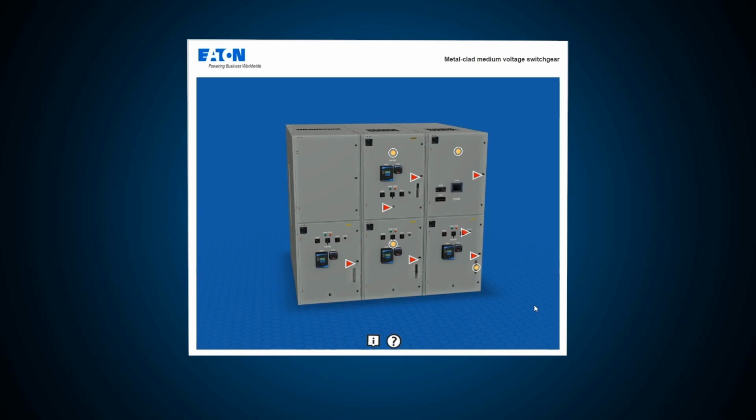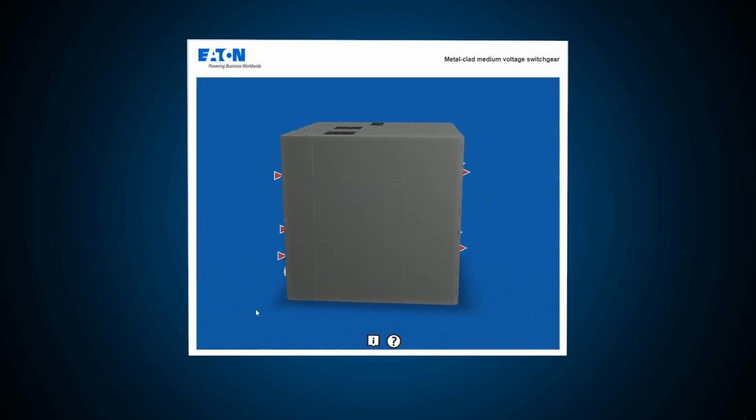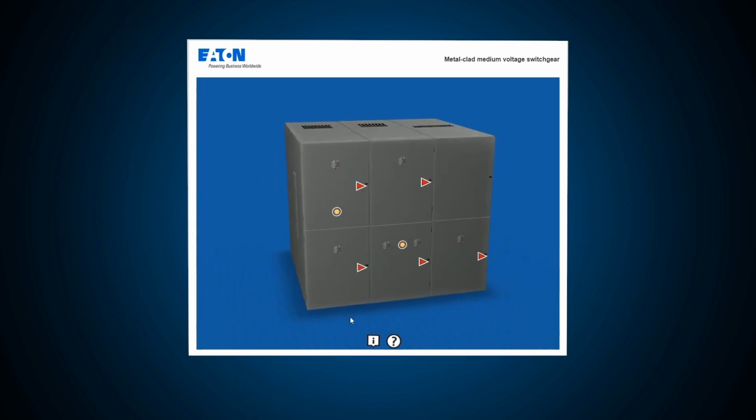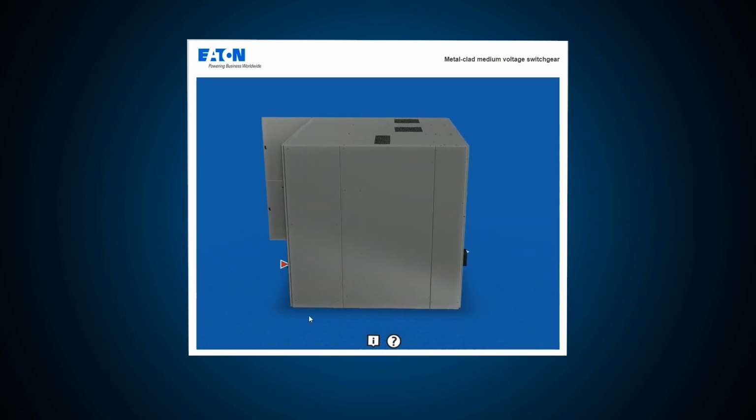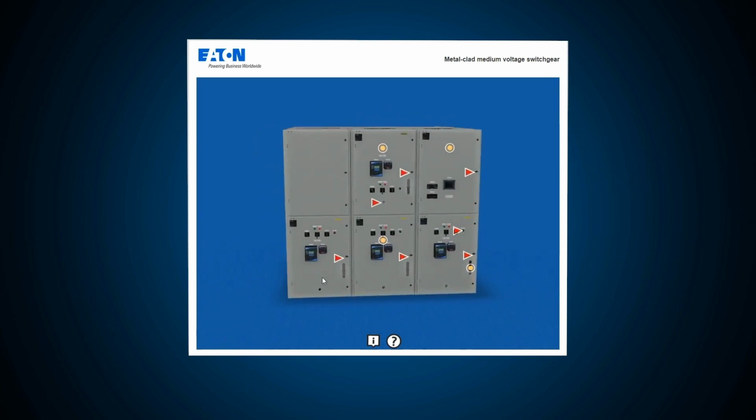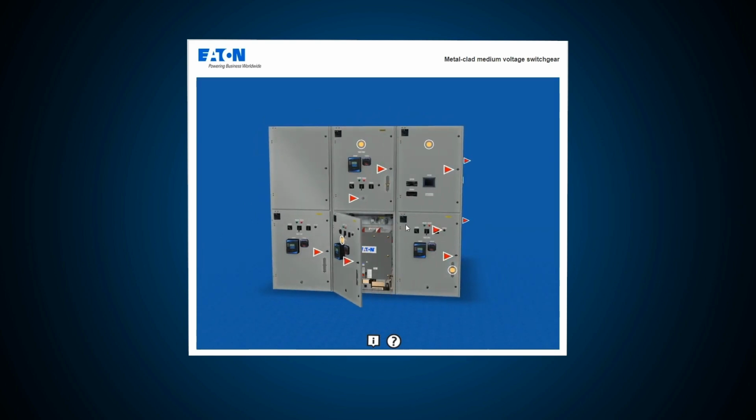Air insulated switchgear, AIS, is defined by the IEEE C37.20.2 standard for metal clad switchgear, and the IEEE C37.20.3 standard for metal enclosed switchgear. In metal clad switchgear, all electrical components, including the incoming bus, the outgoing bus, instrumentation, and main circuit breaker or switch, are enclosed in separate metal compartments to provide an additional level of safety and ruggedness.